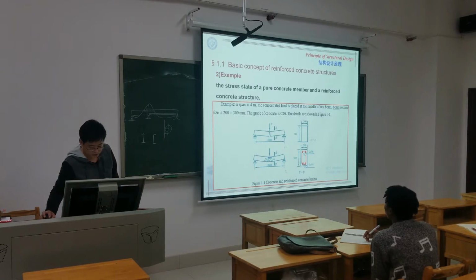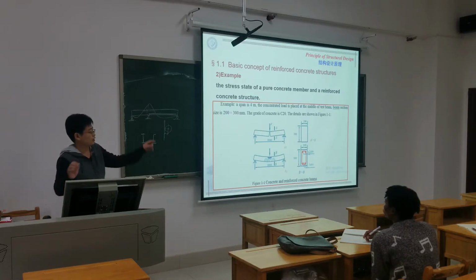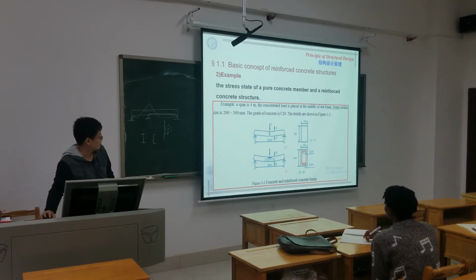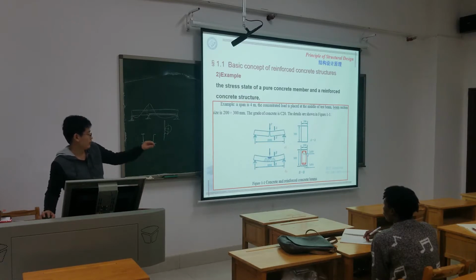But these two steel bars, we see the diameter is 10 and this diameter is 16, so relatively smaller. Those two steel bars, in most cases, are used to fix the stable skeleton. You can imagine if there are no these two steel bars, this circle one cannot stand.